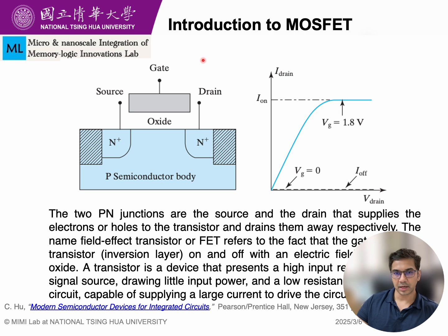Now in reality, the device physics is far more complex than what I am telling right now. It has channel length modulation, velocity saturation, and quantum effects, which become significant at nanoscale dimensions. The graph shows the IV characteristics, but it doesn't really capture the nuance of short channel effects like DIBL and GIDL. DIBL stands for drain-induced barrier lowering, and GIDL stands for gate-induced drain leakage.